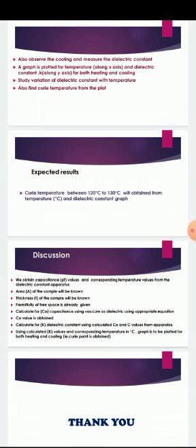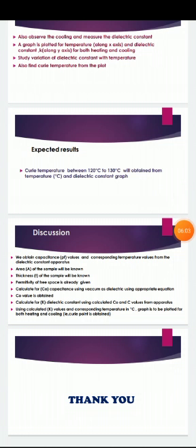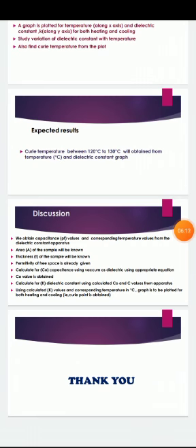By following these steps, we can study the variation of dielectric constant with temperature and also find the Curie temperature from the plot. So, we obtain a Curie temperature of about 120 degrees Celsius to 130 degrees Celsius.